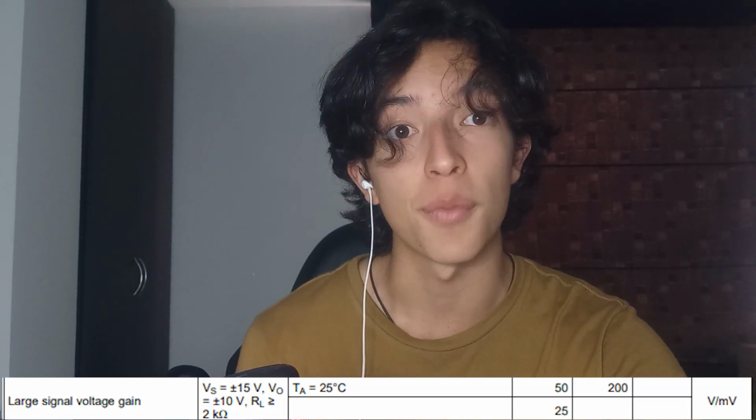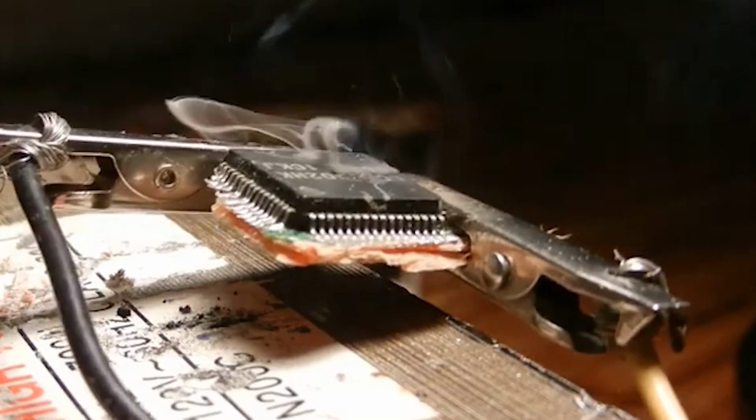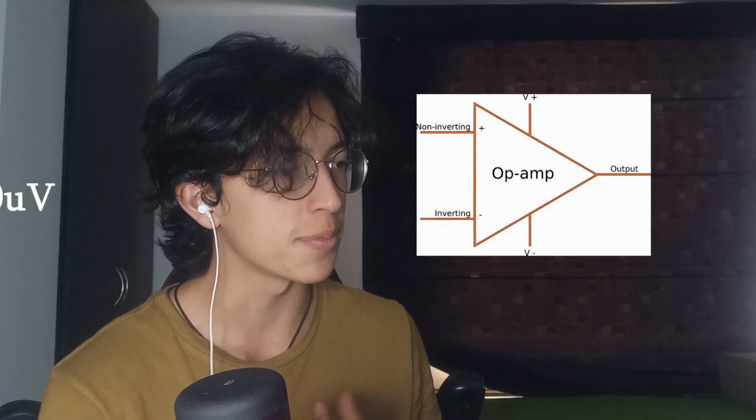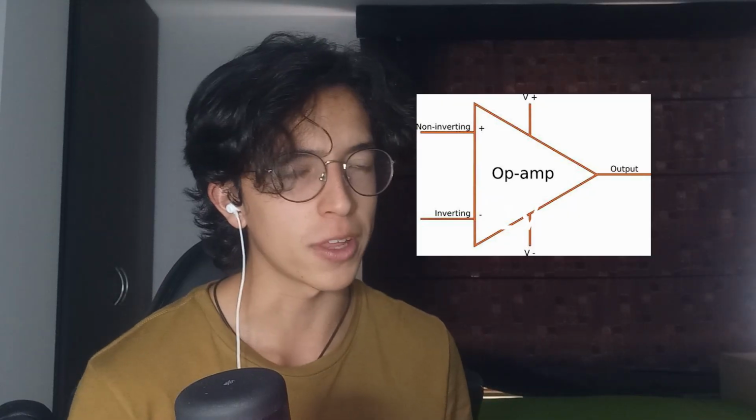The voltage gain of an LM741 is about 200,000 volts per volt, which means you can get this much voltage using a single volt. In that case, you feed your operational amplifier with 200 kilovolts, and we already know what happens. This is not that much of a problem, except if you're working with small signals. Imagine this situation. Most of the human body's electric signals are on the order of 10 microvolts, and that's a lot. So let's say you need to amplify one of those. It's not so easy anymore, right? Because if you plug these signals into the LM741 without any configuration, you might only get about 2 volts